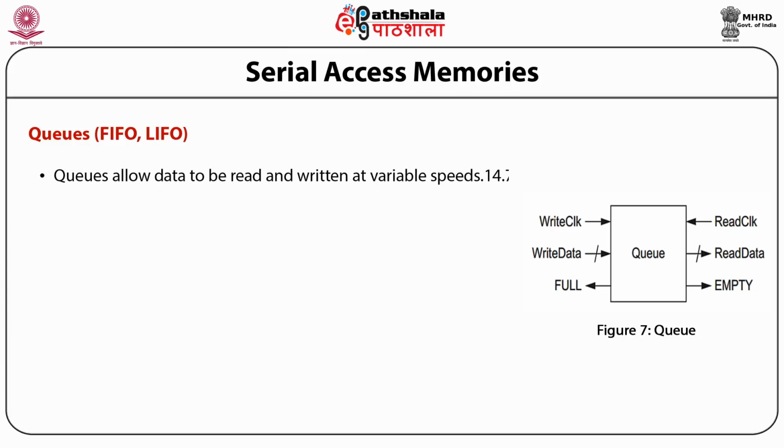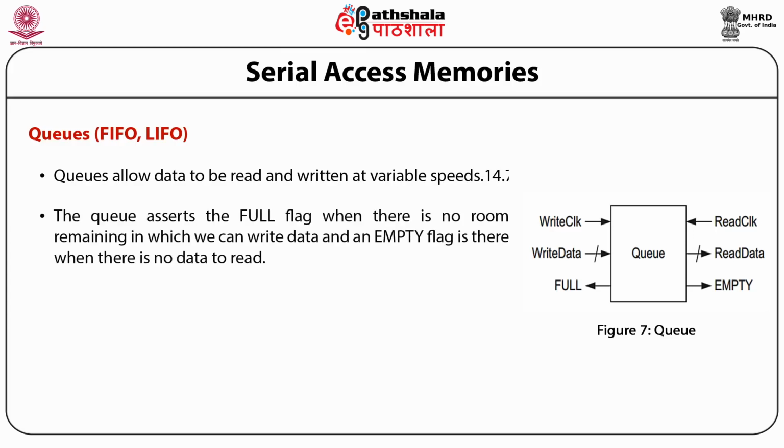This figure demonstrates an interface to a queue. So here the read and the write operations each are monitored by their own clocks that may be asynchronous. The queue asserts the full flag when there is no room remaining in which we can write the data, and an empty flag when there is no data to read.